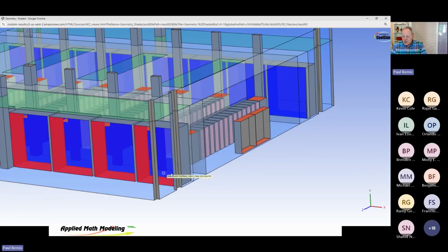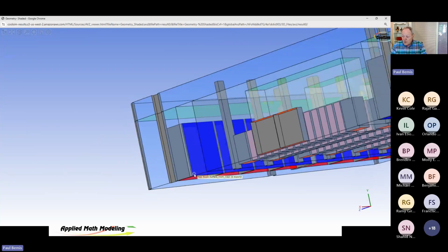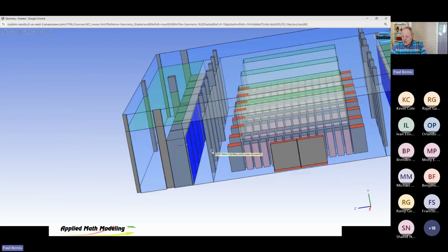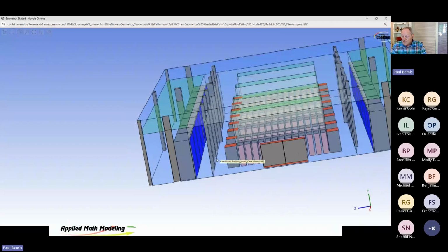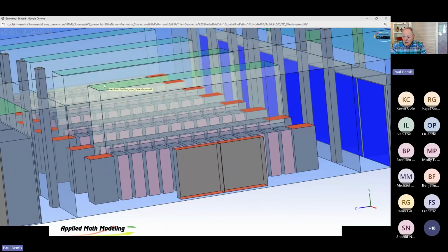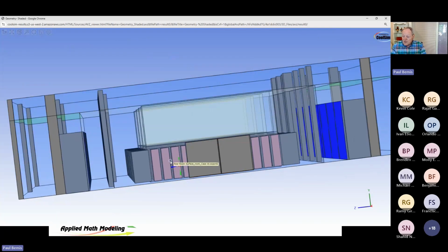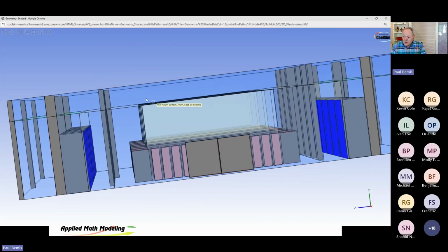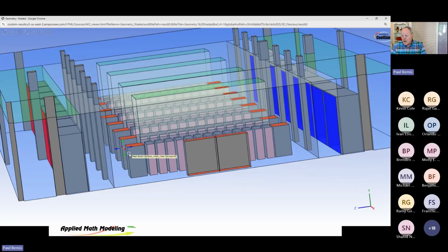Take these devices. These are very large fans with a coil in them. They're really just fan coils. They're blowing air into the room. And this is hot aisle contained. You can see the containment here. These racks are blowing air into the hot side and up through the ceiling. The return plenum goes up around like this. So this is how these operate. Air from both sides, fan walls.